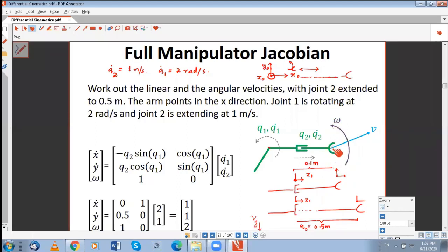So you want the arm to move with a constant velocity upwards, because let's say the wall is here. Or you can do welding, cutting, spraying, you can think of a lot of applications. You just want the arm to move from one point to another point in a straight line, or in a curved line. So you plan the motion here, and then you find the corresponding joint velocities. This is the inverse of what we did here. What we did here was a forward kinematics problem. We knew this, they were given, and we found these. But in practical application, we'll be given this, and then we have to go and find this.